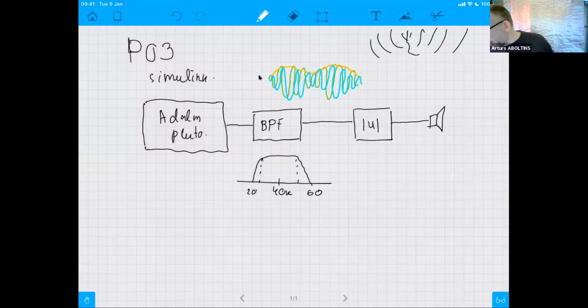So the actual amplitude demodulation was happening in this block. Yes, this was the block which was doing the AM detection, because the bandpass filter is only an auxiliary function to avoid noise and increase the signal to noise ratio, because you do not need to demodulate all signals coming in this band. You just need this amplitude modulation radio station.